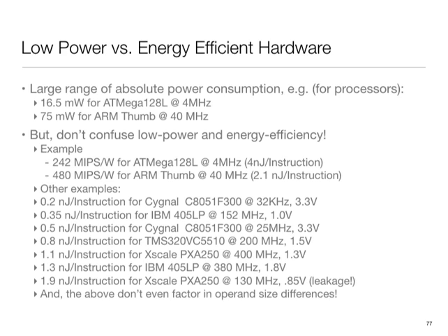I've listed some out here. These are the real low end, ultra low power microcontroller type parts, which often tend to be a fraction of a nanojoule per instruction. But that doesn't mean they are necessarily better, because a bigger processor may be at a few nanojoules or tens of nanojoules per instruction. But the bigger processor probably has wider word width, a more sophisticated architecture, perhaps more cache, and the net effect may be that it does the same task in a much shorter time.